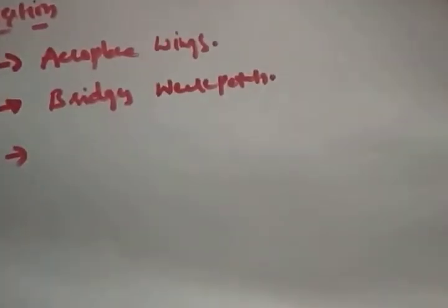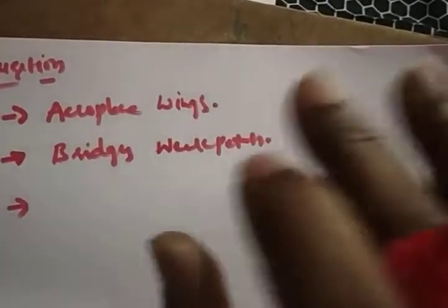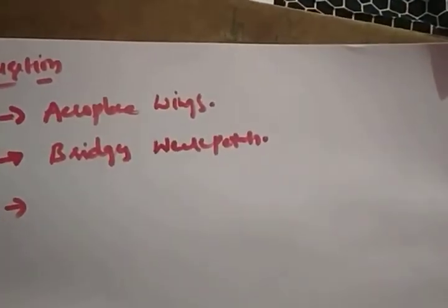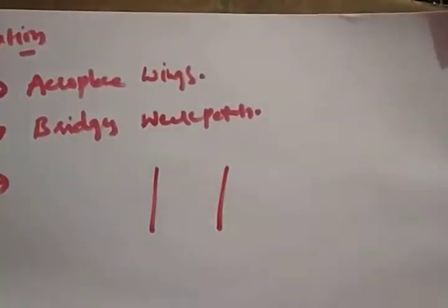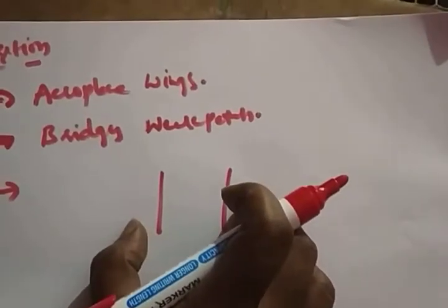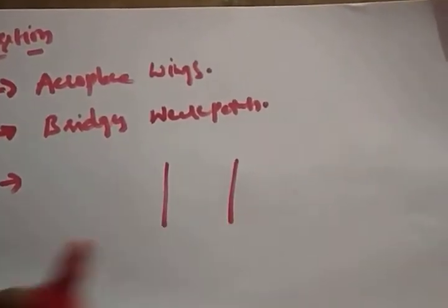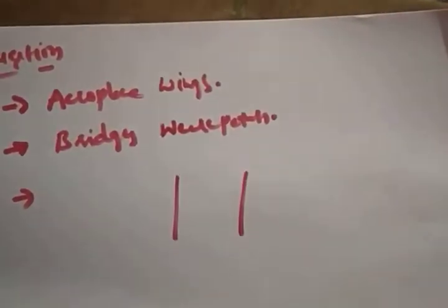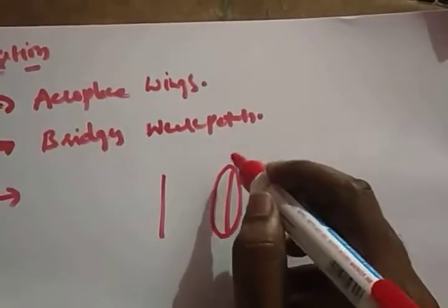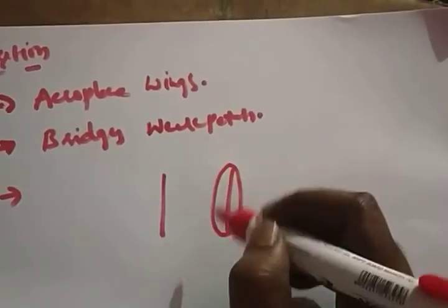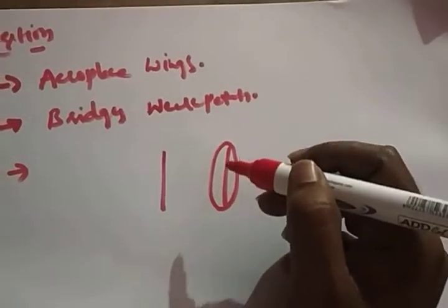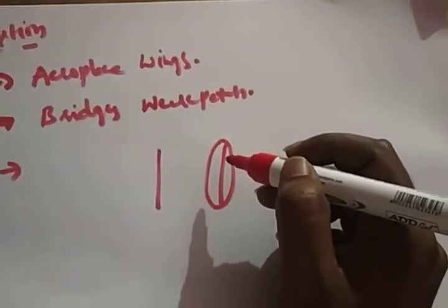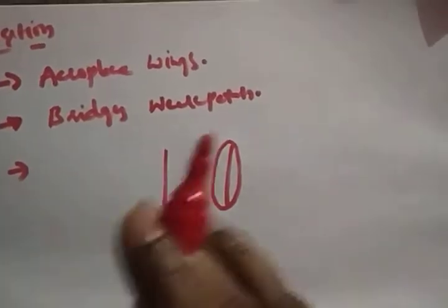So definitely we require the continuous operation of a rail, meaning the rail is subject to horizontal forces and vertical forces, right? So whatever the tracks, there are two tracks. So these tracks should withstand the weight of that rail, or the forces that are acting on that rail, right? So definitely we require a sensor to tell whether this track is maintaining that stress or strain. We should know. So definitely that is the engineer's duty. So we require a sensor, and that sensor is nothing but a strain gauge,